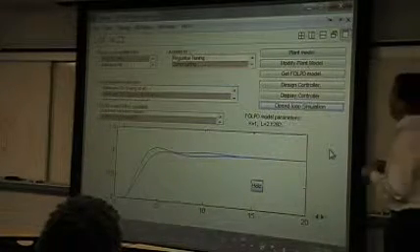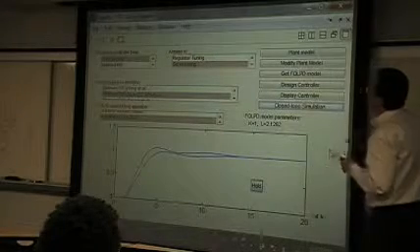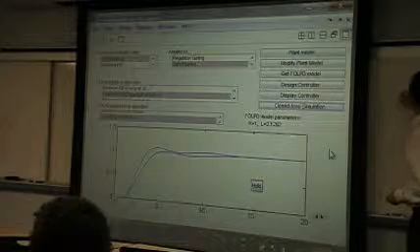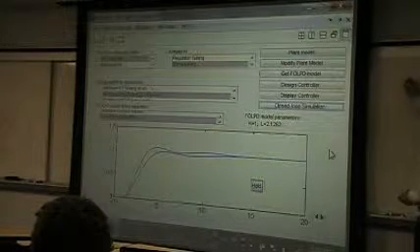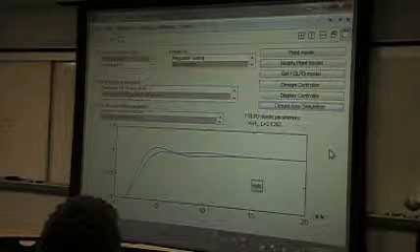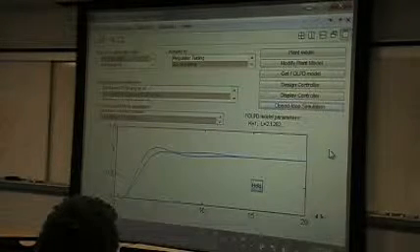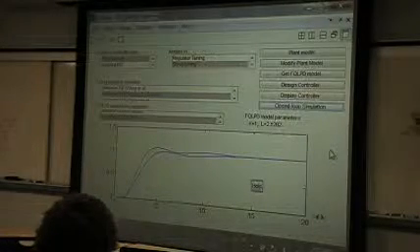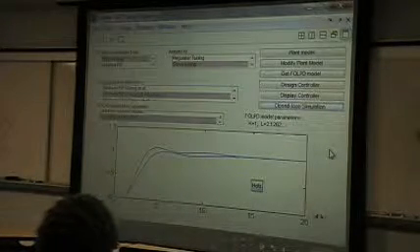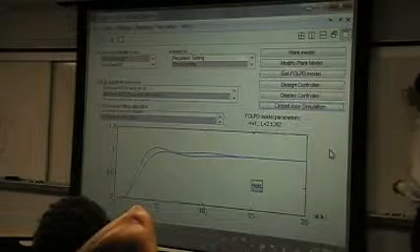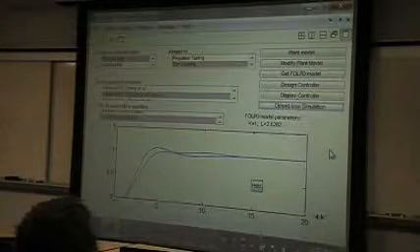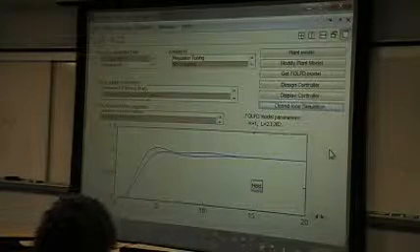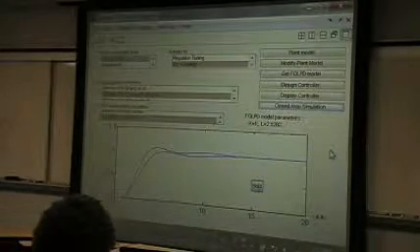In this program, I only implemented the plant model which can be fitted like this. Even if there are oscillations or something like this, since the PID controller has certain robustness, we can still use it. However, if the system cannot be approximated well with this kind of model, this program cannot be used. So there are limitations in the program.